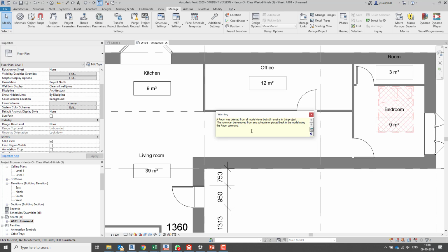So you are deleting the room from all the views. That's okay. What I did was remove the balloon from the room, but I still store that balloon in the project. It's still available for me to put somewhere else. In order to delete the balloon, I can only do it in schedules. It's a feature of Revit, and I tend to agree.